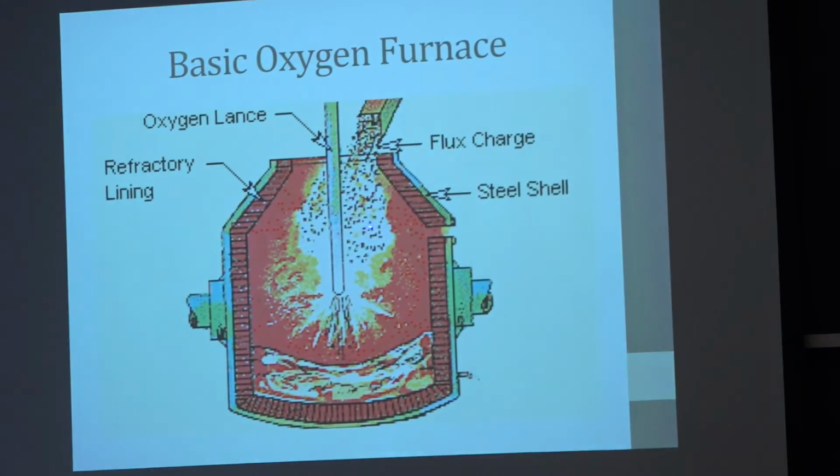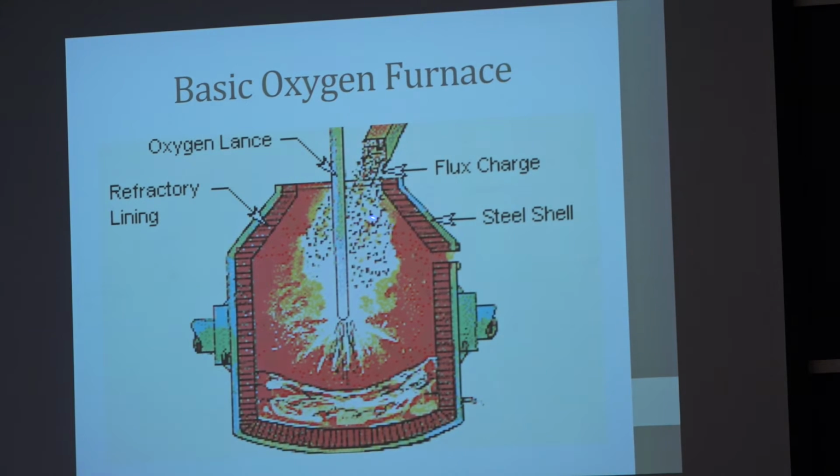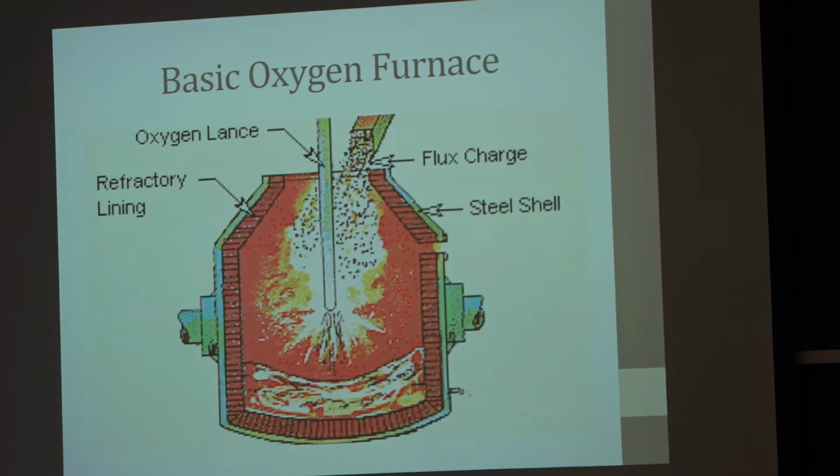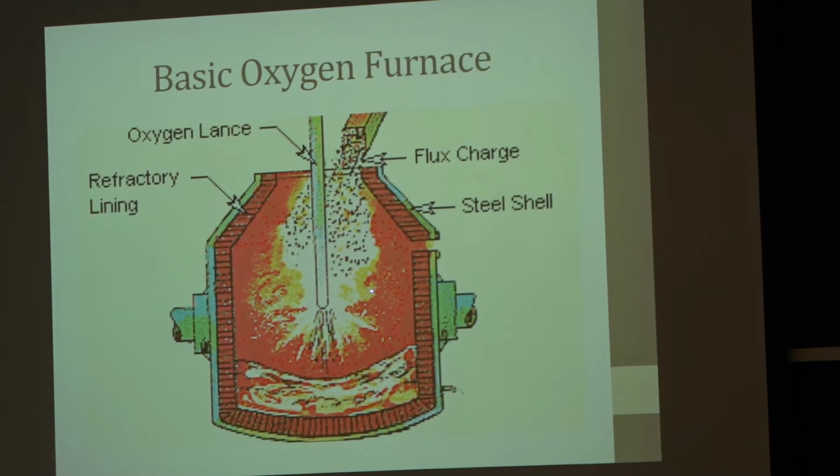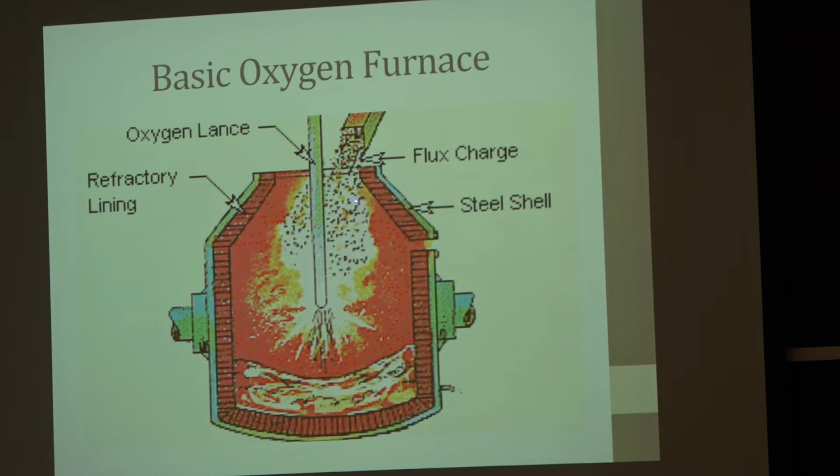Well, people innovated and they came up with more efficient ways to do it, and that's essentially what happened in the steel industry. The Austrians came up with the basic oxygen furnace. The process for liquefying air had been developed in Germany back in the World War I era, and they decided that rather than puddling the steel with air to burn the carbon out, they'd use pure oxygen, okay? And so they blew oxygen in.